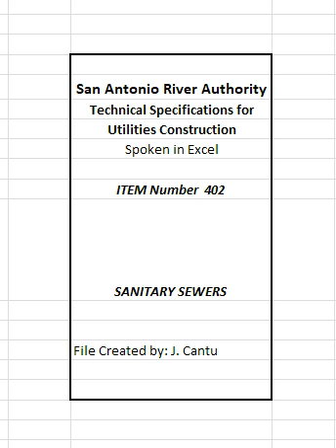C. Where a sewer crosses under a water line and the sewer is constructed of ABS truss pipe, similar semi-rigid plastic composite pipe, a minimum 2-foot separation distance shall be maintained. The initial backfill shall be cement stabilized sand, 2 or more bags of cement per cubic yard of sand, for all sections of sewer within 9 feet of the water line. This initial backfill shall be from 1/4 diameter below the center line of the pipe to 1 pipe diameter, but not less than 12 inches, above the top of the pipe.